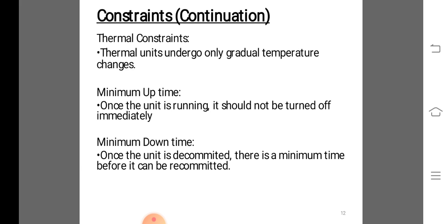There are two approaches to treating a thermal unit during its down period. The first allows the unit's boiler to cool down and then heat back up to operating temperature in time for a scheduled turn on. The second requires that sufficient energy be input to the boiler to just maintain operating temperature.